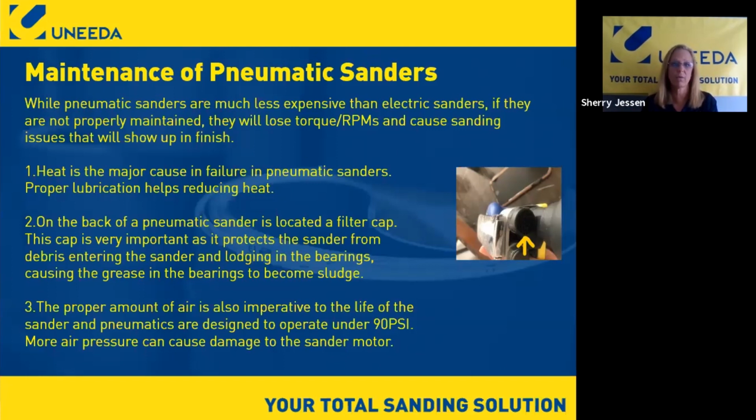So when I talk to him, I ask, what are you seeing? He can usually give me an idea of what he sees in the wood as it comes in and what he has to fix if it's a stain job. With the amount of paint today, it's not as crucial, but you still have your stain jobs where it is. You can tell by the amount of swirls, or the way the swirls are laid out on the workpiece, whether you've got a slow RPM sander, problems with your sanders, or if it's just over-sanding. You can look at the actual pattern and tell. And that's huge, because when you go into your custom shop, you want to be able to fix what's broken.